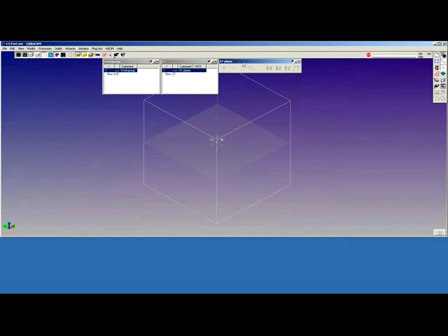The coordinate system palette has a series of tiles that perform actions on the coordinate systems. We have the change origin tile, align the horizontal axis of a coordinate system to a piece of geometry, align the vertical axis to a piece of geometry, align a CS plane, whether it's through a series of points or a rotation. And then we have the planar orientation tiles, XY, XZ, and YZ, which control orientation along the three primary planes.